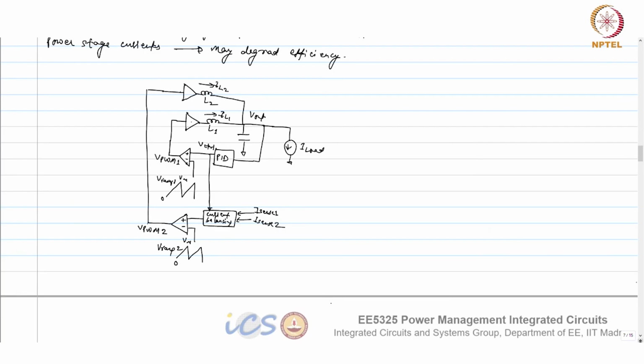So that is why, even if it reduces your efficiency a little bit due to mismatch in the inductor, you don't care, because that impact is not as high as a mismatch in duty cycle. But if you have a way where you can determine whether this mismatch is due to RDCR or due to duty cycle, that is also quite possible. You can measure the duty cycle at the switch node. You can always measure the duty cycle at these two, VSW1 here and here. Ultimately, you are interested in the end duty cycle.